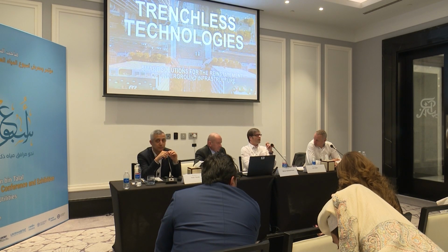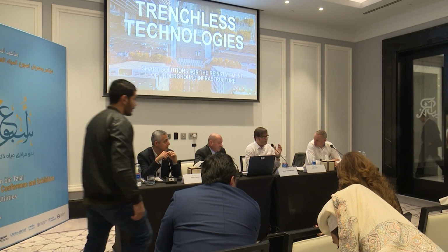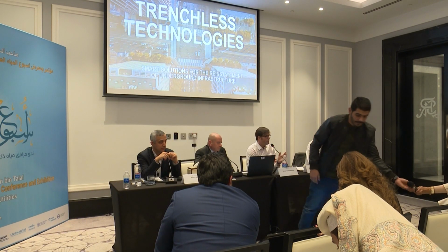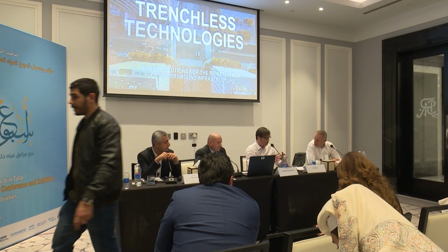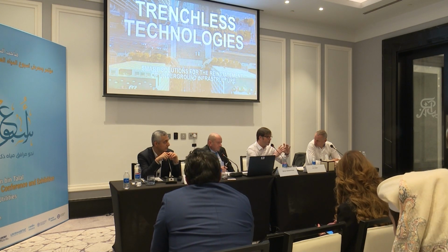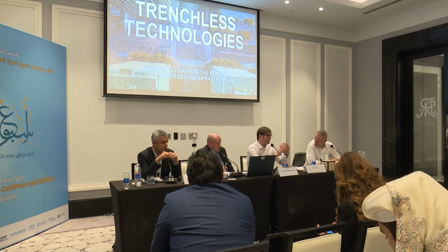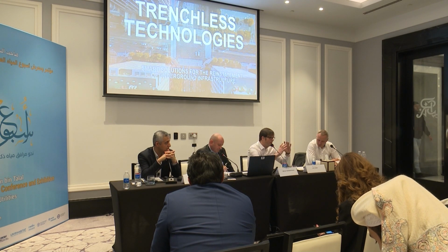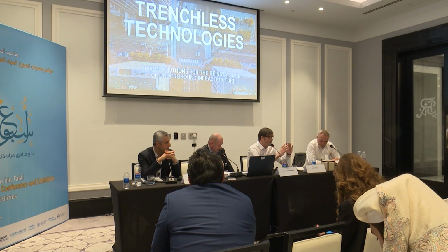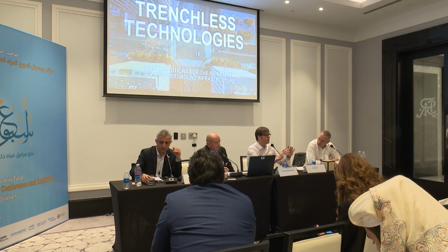That is one of the disadvantages of pipe bursting. Even when you replace like for like diameter, you are always displacing soil. You are displacing the old pipe into the surrounding soil. And that is important. You need soil or a material around the pipe that allows for that displacement. So if a pipe has been laid into concrete, for example, that can't be displaced.